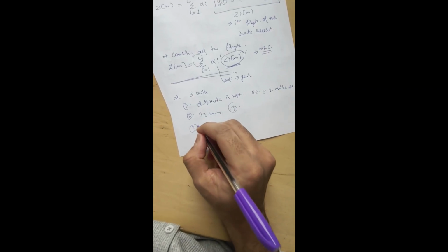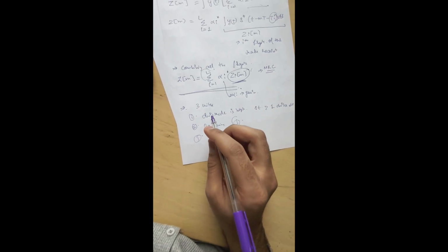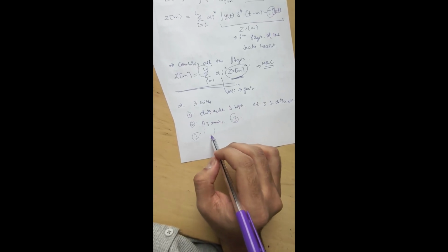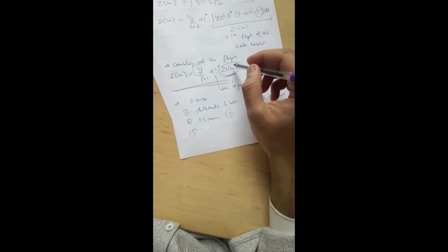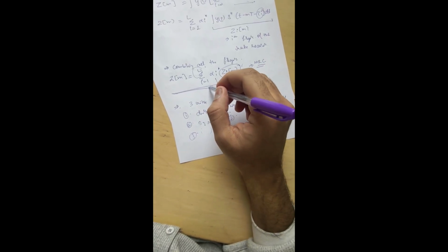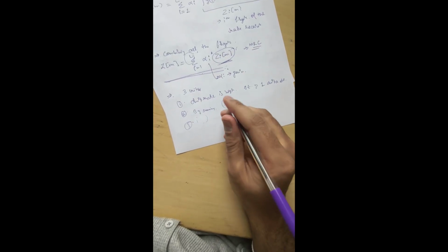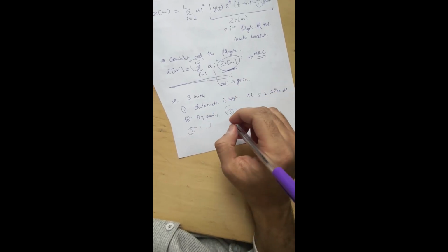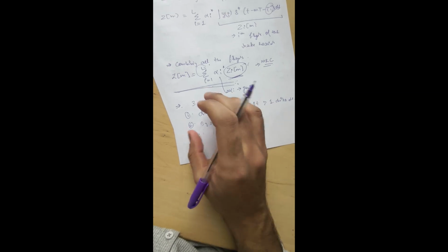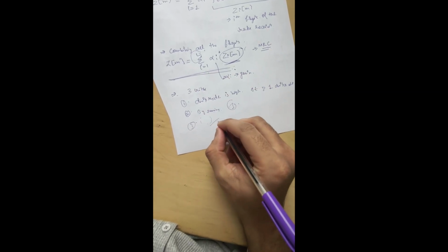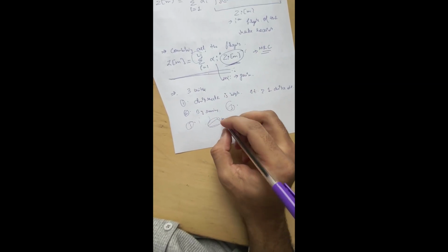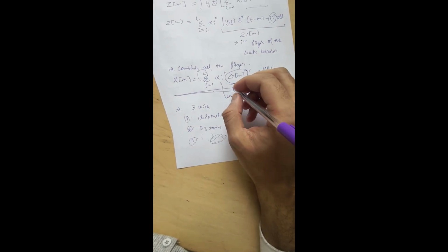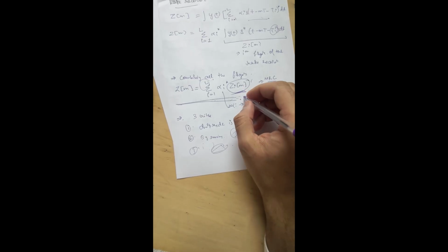Finally, just to provide an analogy, the reason why it is called a Rake receiver is that each of the individual fingers rakes up, or consolidates, the energy from different multipath components and piles it up, so that in the output we get a summation of energy from different independent paths, and so we get the required SNR that we want.